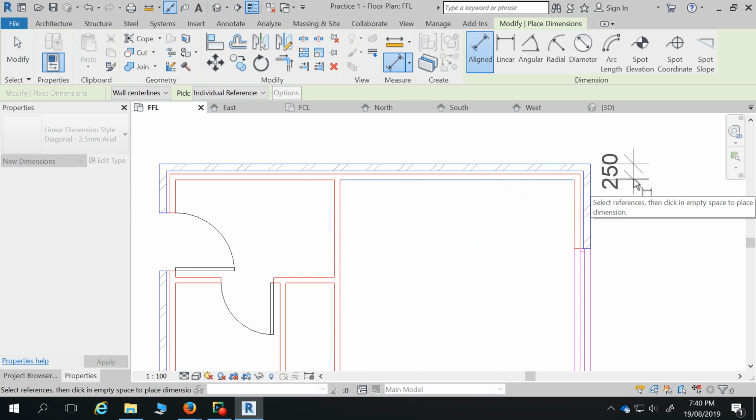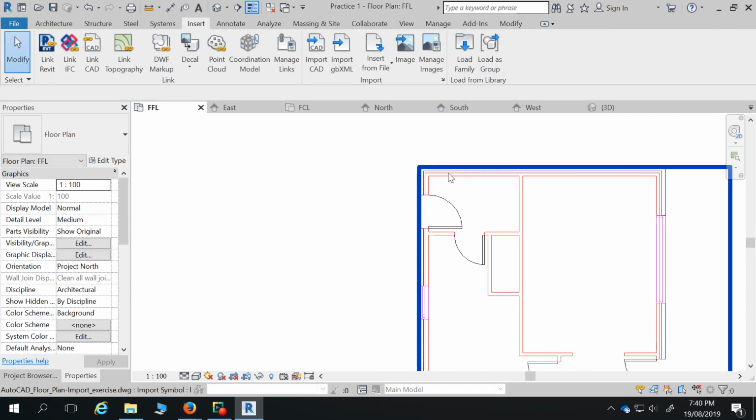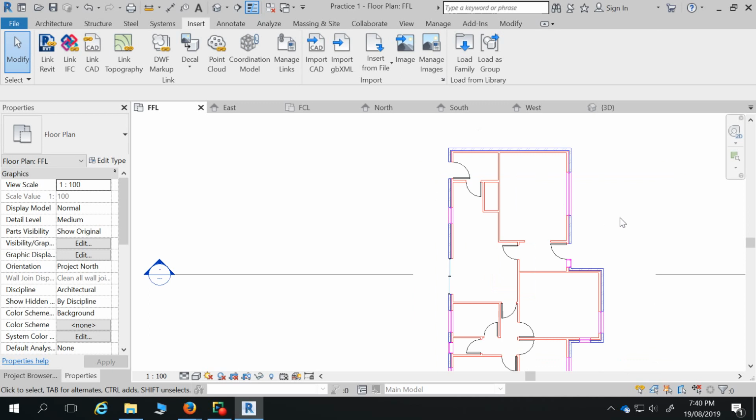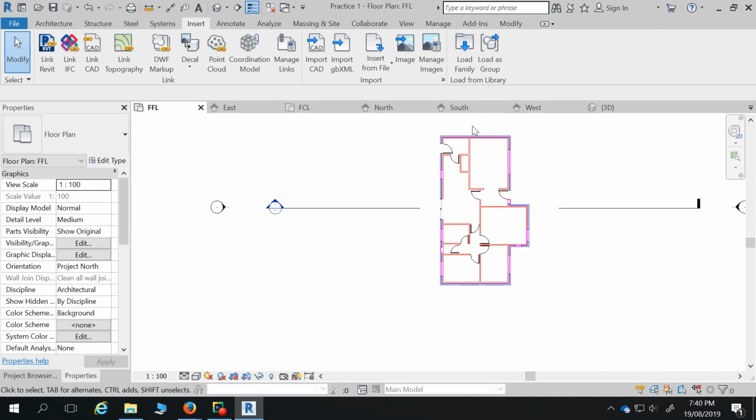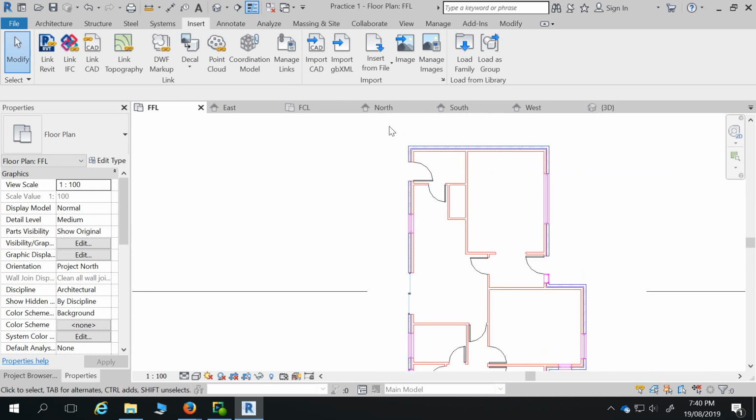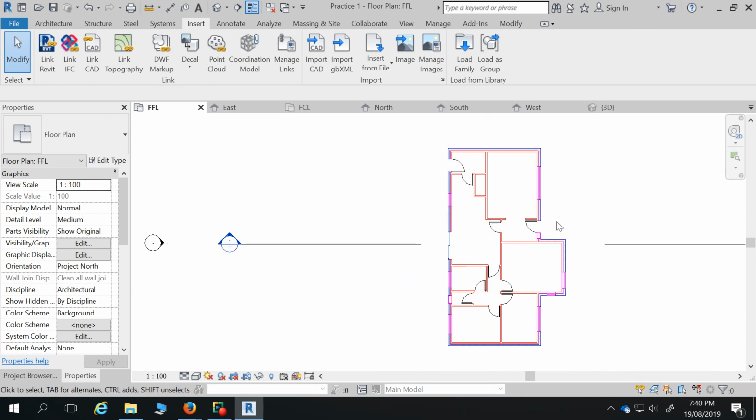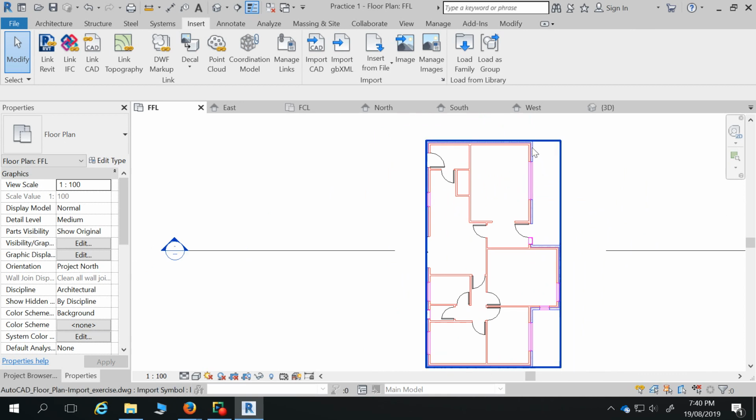The brick veneer wall type that we used before as practice will be the same wall type we use. So we'll start using the wall tool, but we can actually do pick lines. When we do pick lines, we've only got to pick one side at a time. We want to draw straight over the windows.